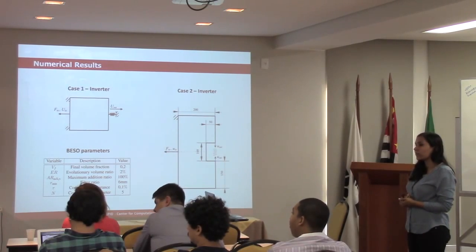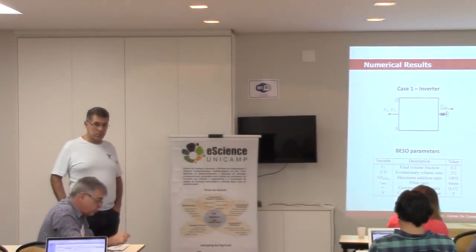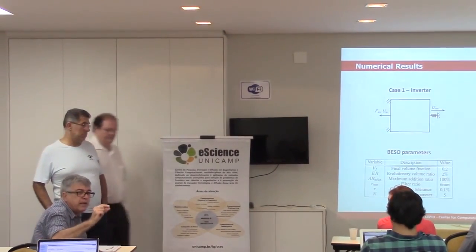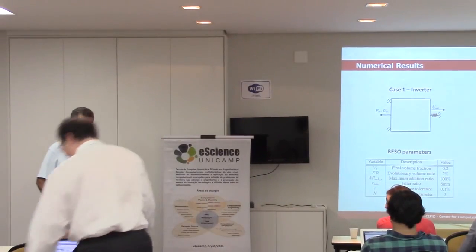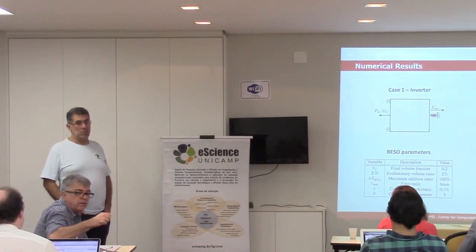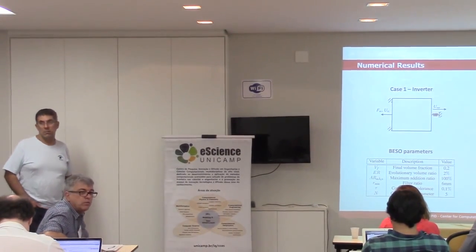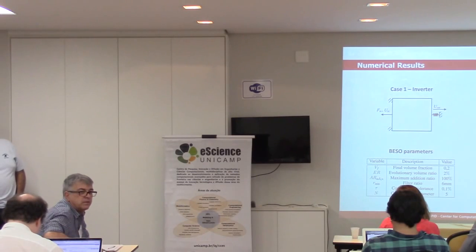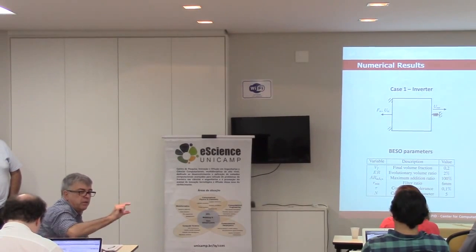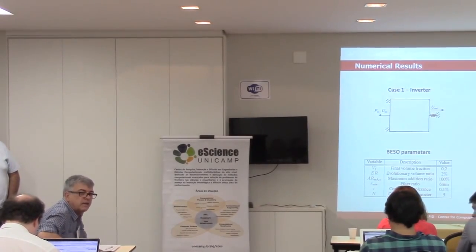This kind of mechanism is normally used for small sizes, micro mechanisms, like to manipulate cells or in microscopes, things like that, because the displacement is very small and the force is also not too large. They did that with the additive manufacturing process. So the inverter inverts the direction of the force applied? Yes. And the gripper catches something, like a piece? Yes, exactly. Okay. Thank you.